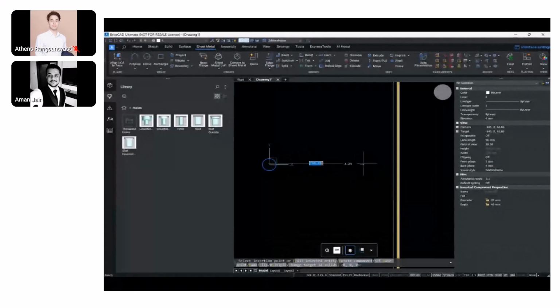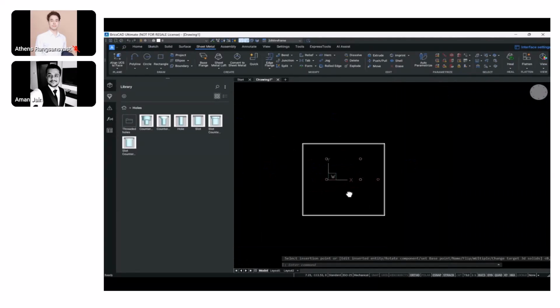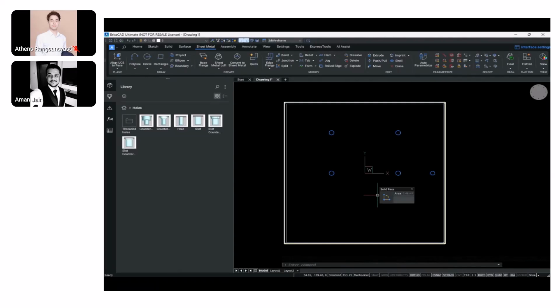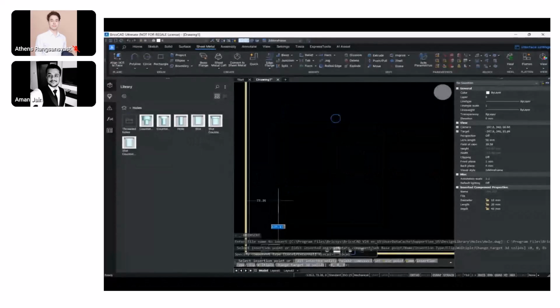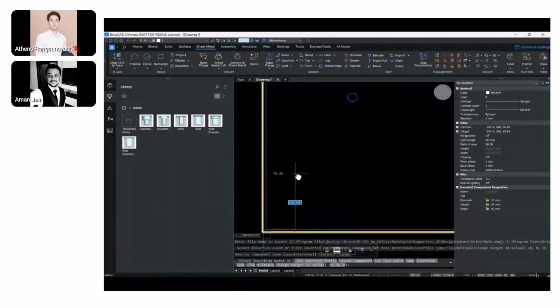So here I'm placing one more hole, which is for the lock, right? Where the lock would be placed in. Let's say this would be at a distance of around 140. Now, this is smart placement of the holes as well. Ideally, I'm able to place this in conjunction with the holes that I had already created, and I can add distances based on their positions. So this relatively becomes easier for me rather than creating sketch geometries for each and every feature that we add, right?